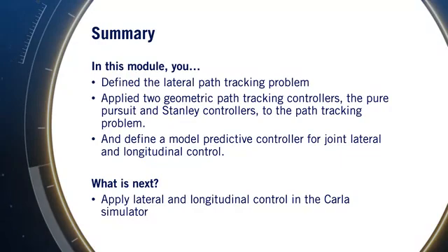Congratulations, you've made it to the end of the module. In this module, you learned how to define the lateral path tracking problem, apply 2 geometric path tracking controllers, the Pure Pursuit and Stanley controllers, to the path tracking problem, and define a model predictive controller for joint lateral and longitudinal control. In the final module in this course, you'll get your first hands-on look at the Carla simulator, where you'll design lateral and longitudinal controllers to navigate a vehicle around a racetrack.